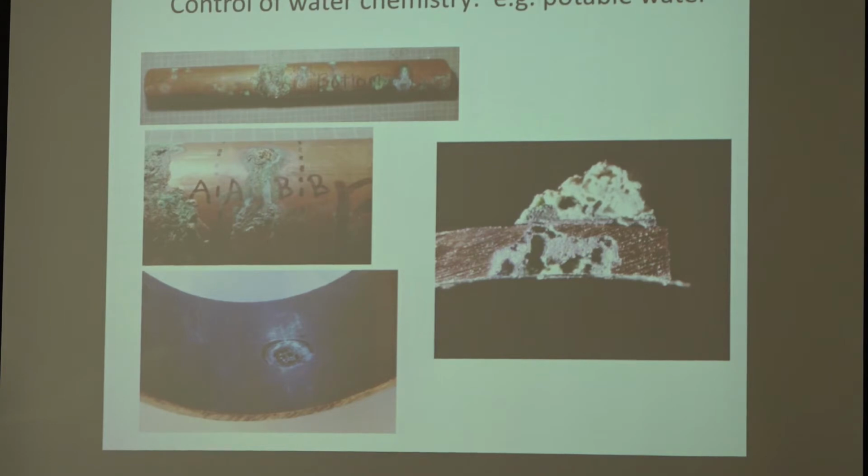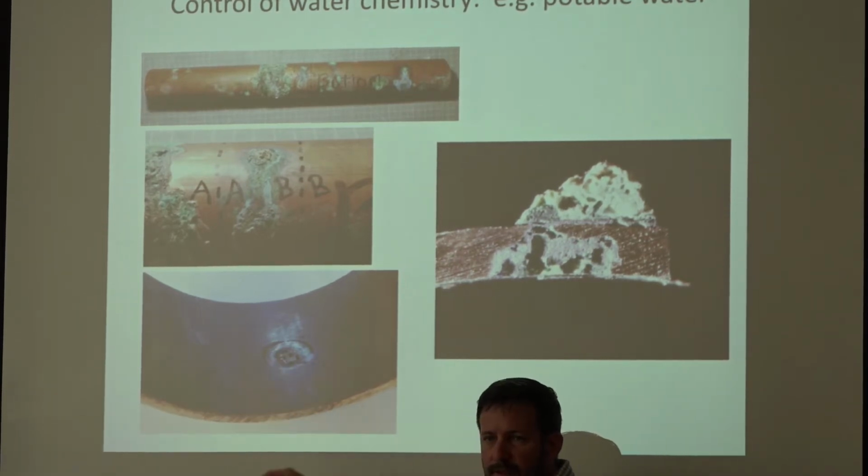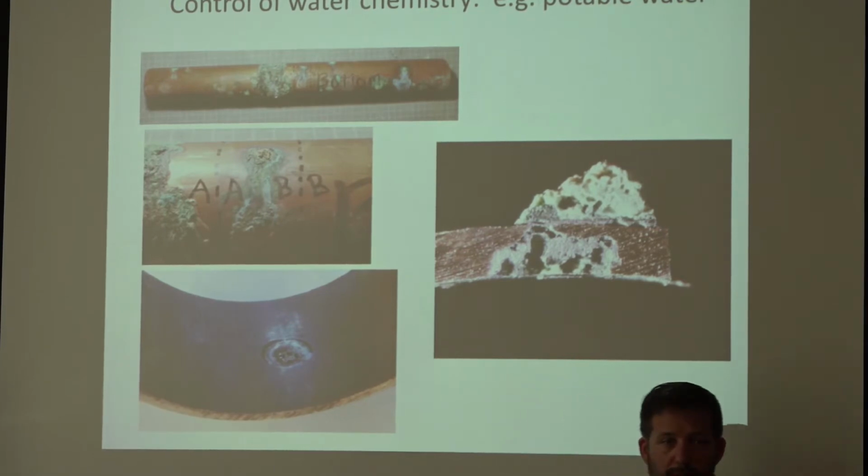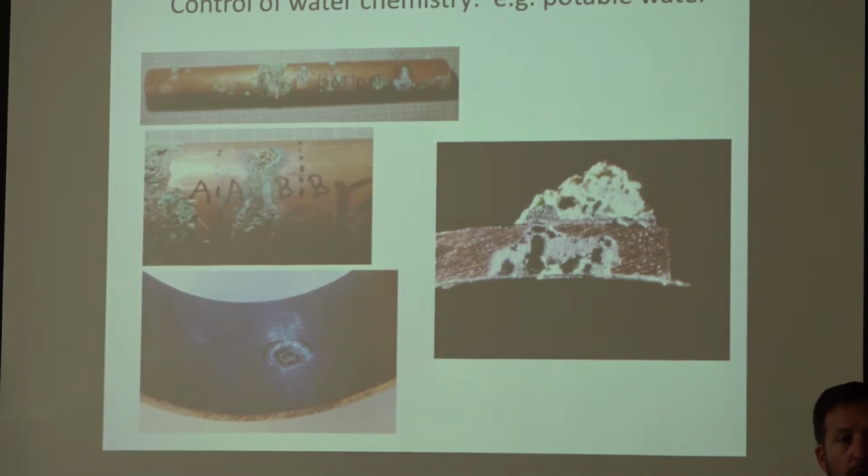It didn't adhere all the time. So in that case, if you just brush off the outside to clean it up, then all of a sudden you start leaking again. So I mentioned that it was a lot of use. There were deposits inside the line from a lot of usage, a big flow rate. And that was one of the triggers. And I say triggers because there's more than one in this particular case of why this plumbing deteriorated very quickly. It didn't have much to do with the quality of the copper.